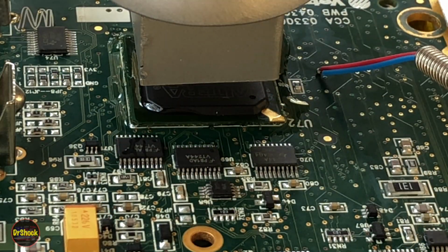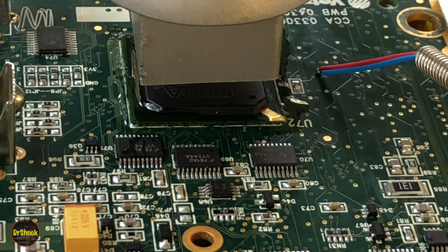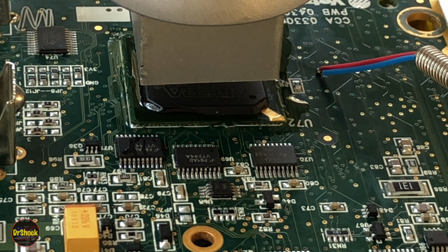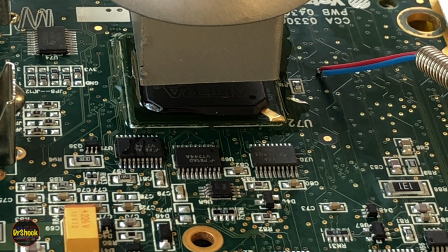All right, guys, just showing you a checkup here. We're not quite to the board soaking temperature yet, so we don't have the hot air gun on, but I had to position it beforehand because I don't want to knock the probe out of the way that's next to it. So we're just going to let it continue to ramp up here before we fire it up.